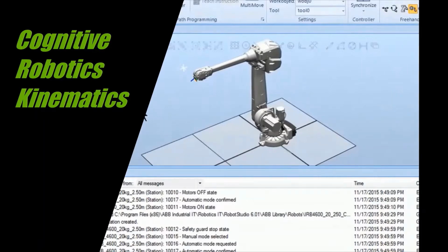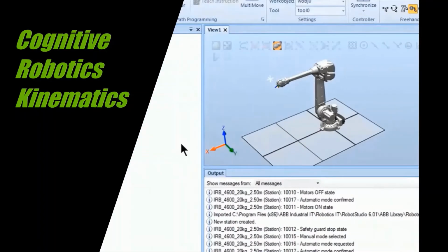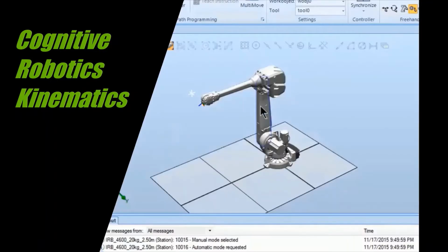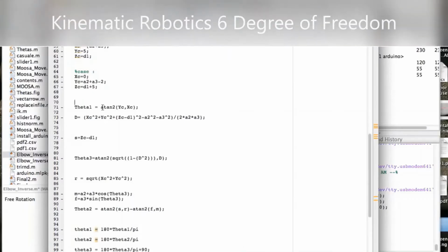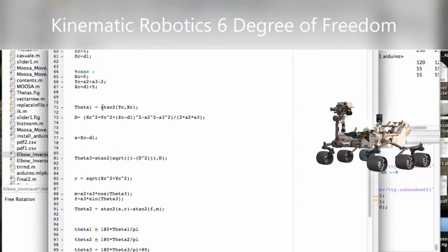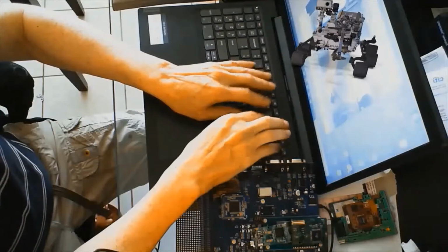With a vision sensor attached to the arm, the actual position and orientation of the target are detected. The velocity commands are generated in the sensor in order to move the arm towards the object. Another example is a force sensor attached to the end of the arm and used to assemble a shaft onto a long hole.